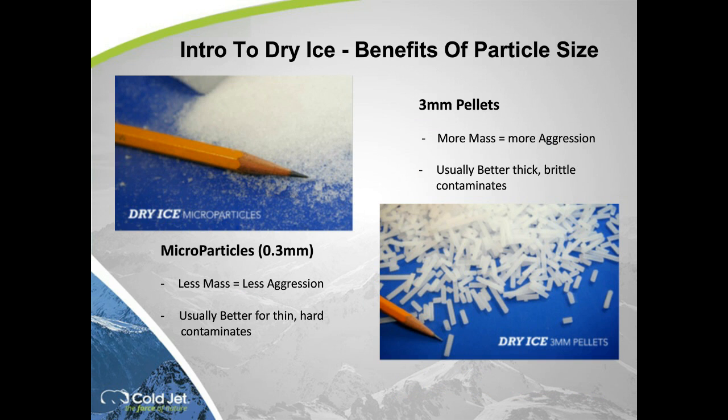The block will give you microparticles. When you shave it, you'll end up with 0.3 millimeter size particles. Really good for thin, hard contaminants you'll find on tooling. Really good at taking off burrs and flash. Most popular in the medical device industry.